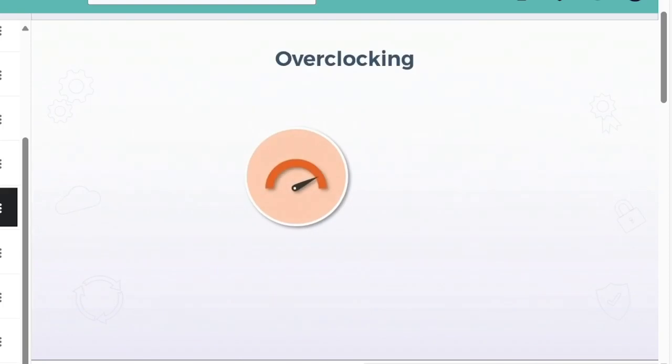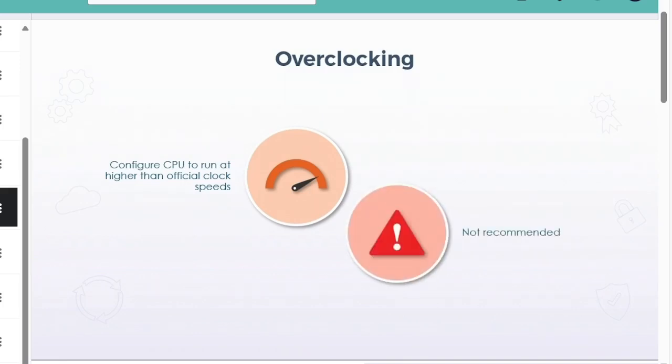Another feature that you may have encountered more so with older processors is overclocking. And this quite literally means that the CPU can be configured to run at speeds higher than their rated or recommended speed. Now, this is not very common anymore for several reasons, most notably because the speeds are so fast these days compared to the days when overclocking was common that it just isn't necessary. And perhaps more so because it was never really a recommended strategy anyway, because it could void the warranty and could potentially damage the processor or other system components, because the more you increased the speed, the more heat you would end up generating. Now, if you had adequate cooling, you could usually get away with it, but the increase in performance would be marginal at best, and possibly not even noticeable for most applications.